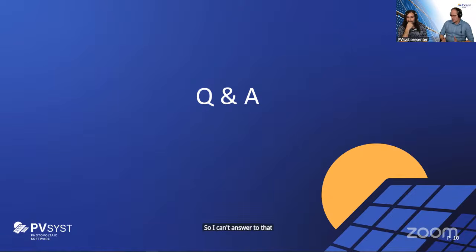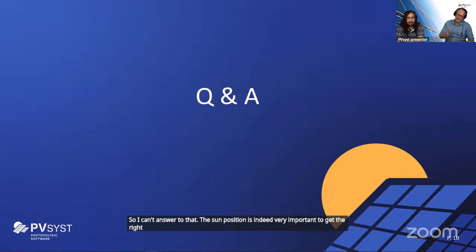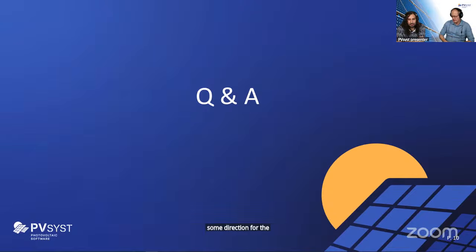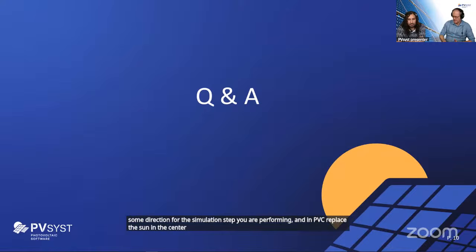The sun position is indeed very important to get the right simulation. You have to have a representative sun direction for the simulation step you are performing. And in PVsyst, we place the sun in the center of our time interval. So if it's an hourly time interval, it will be half an hour from the borders. If it's a 1-minute interval, it will be 30 seconds from each border, but it's always centered on the time interval we are simulating.